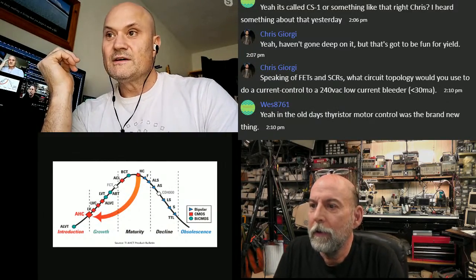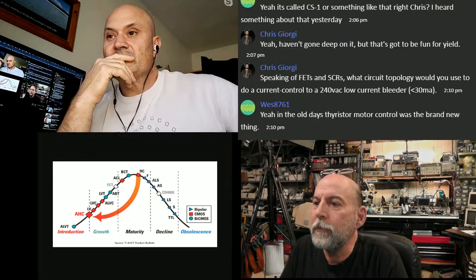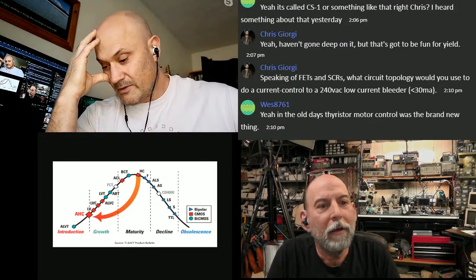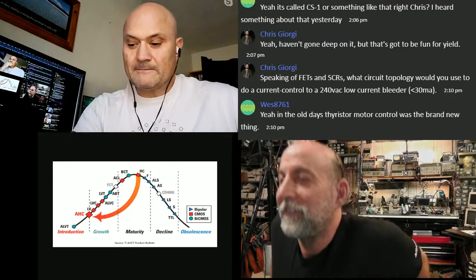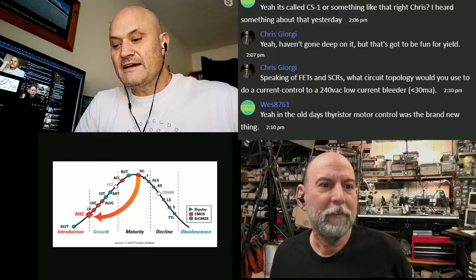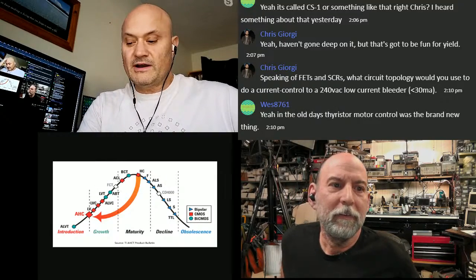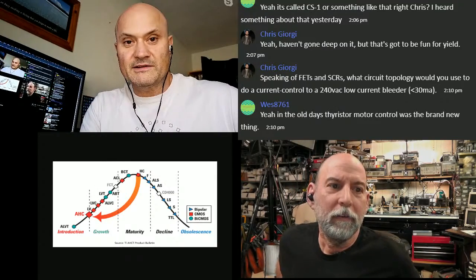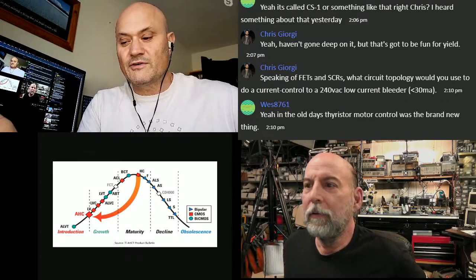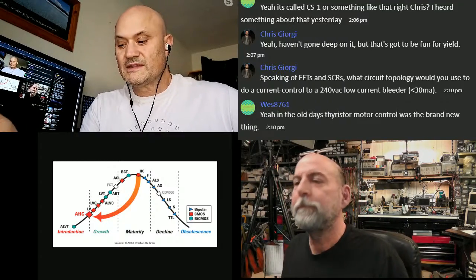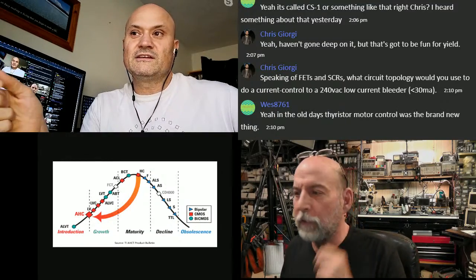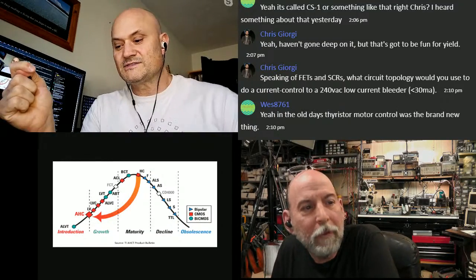Yeah. So looking back at this, remember the CD 4000 series? Yeah, those were awful. They were hard to use. It had some good advantages though, if you wanted something that didn't have to be fast but operated at high voltage. So a lot of guitar pedals use 4000 series CMOS chips because you can run them all off the same 9-volt battery as the op amps. So that's a classic use case for those, that 5 to 15 volts. Yep. They don't have to be fast.